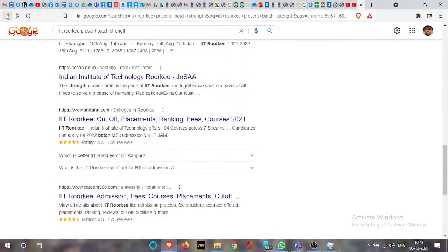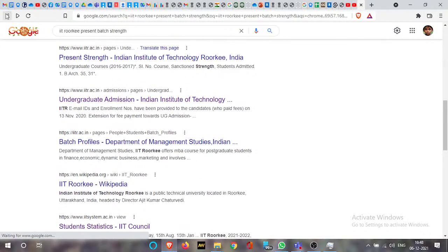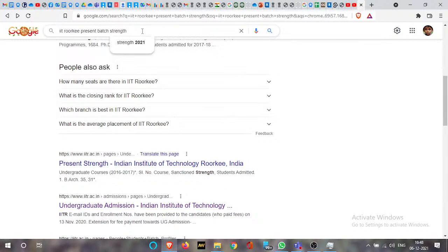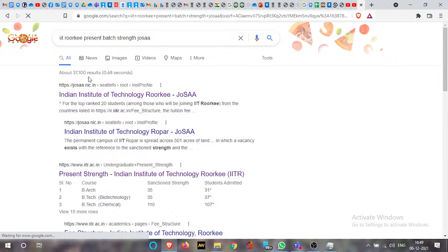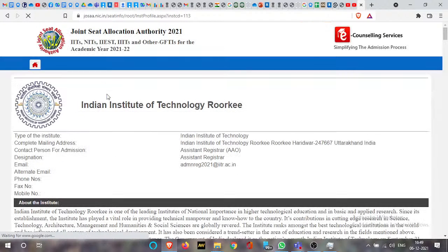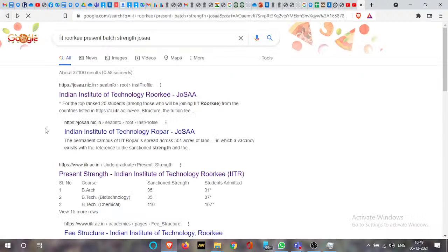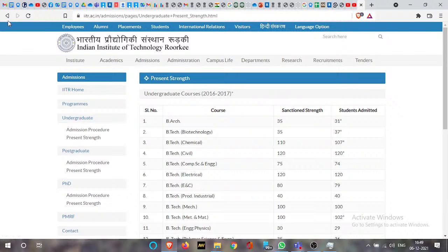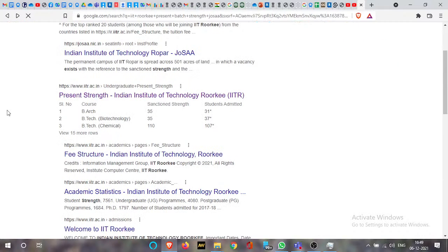And then you have this tunnel magnetoresistance ratio calculated as R antiparallel minus R parallel divided by whichever is higher or whichever is lower. So he observed a change of about 11.8% in this structure, in this tunnel junction. So you see this change is about 11%, which is significantly higher than the giant magnetoresistance. So this was the turning point.